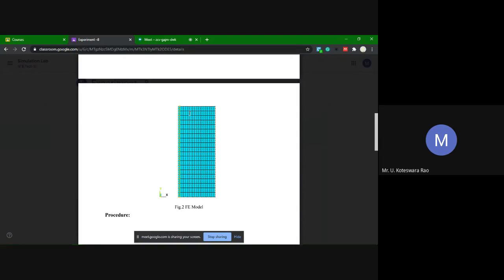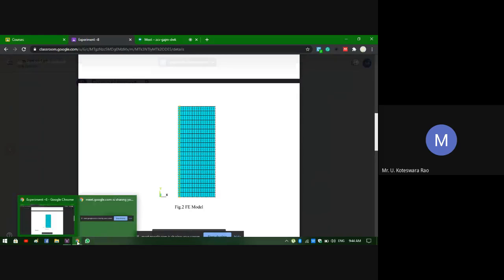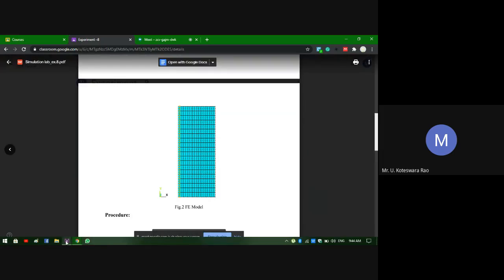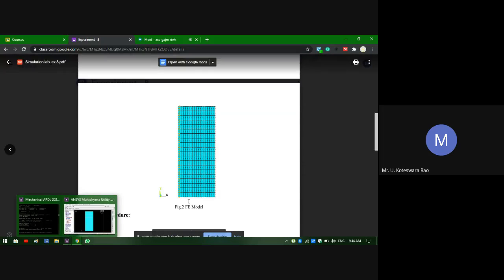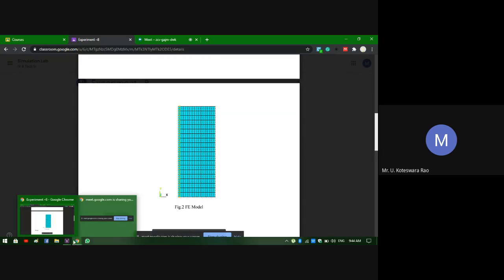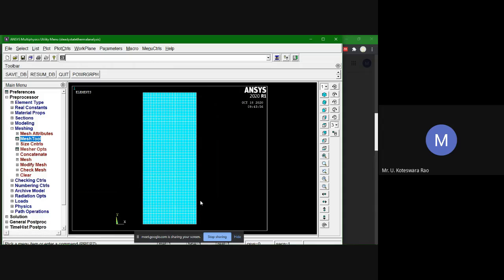But in the vertical direction you have a smaller number of elements. You can do that also, because we already discussed that temperature is independent of the vertical direction, that is the length. So you can have different mesh sizes in the horizontal and vertical directions. Here we are given uniform, but even with the same solution, no problem.